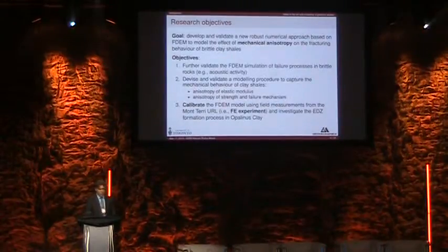So the real goal was to further develop this method and validate it, and specifically look at the effect of mechanical anisotropy on fracture nucleation and propagation in shales. To achieve this goal, three main objectives were set. First, we wanted to further validate the method in terms of whether it is actually able to capture brittle failure in rock, not necessarily anisotropic.